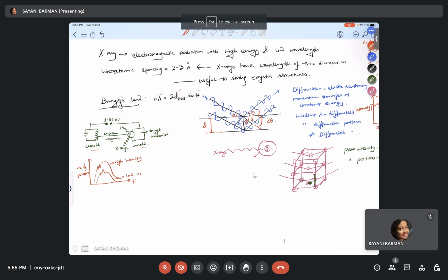Please do listen. The sample is placed in the instrument and illuminated with X-rays. The X-ray tube and detector move in a synchronized motion. The signal coming from the sample is recorded and graphed, where peaks are observed related to the atomic structure of the sample. Most materials are made up of many small crystals, right? Each of the crystals is composed of a regular arrangement of atoms, and each atom is composed of a nucleus surrounded by electron clouds. X-rays are high energy light with a repeating period called the wavelength lambda.